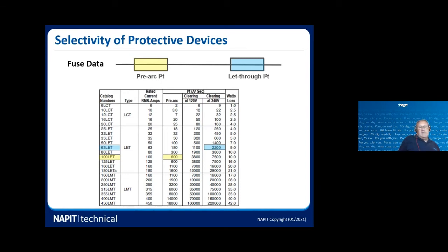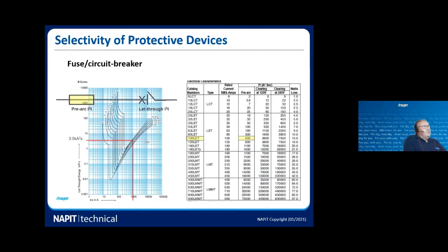And as Paul said at the start of this seminar, really, if you try to have a 100 amp supply fuse and you try to have a switch fuse after that, because they're consuming it in a remote location, it'd be very, very difficult to provide selectivity between the 100 amp supply fuse and a fuse in that switch fuse. But do we need to? Okay, is the question there. Next scenario, if you wouldn't mind, Paul.